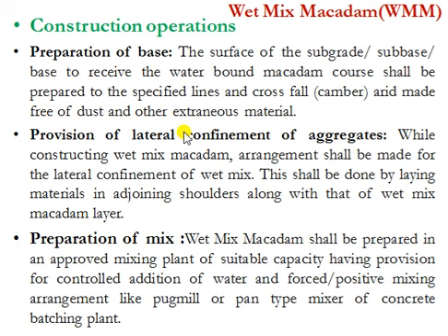The surface should be made even by considering the camber, and if there is any unevenness in the base or subbase, it should be made proper, and then the wet mix macadam layer is laid. So this is how the preparation of base is done.